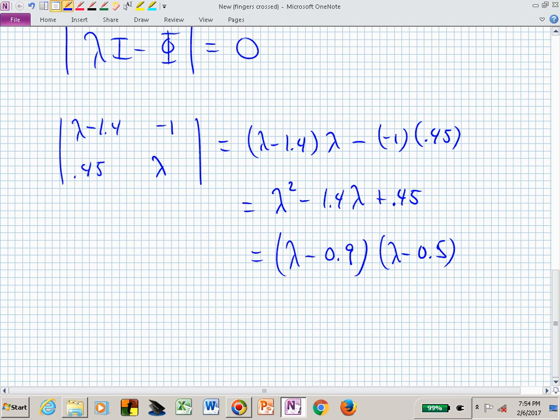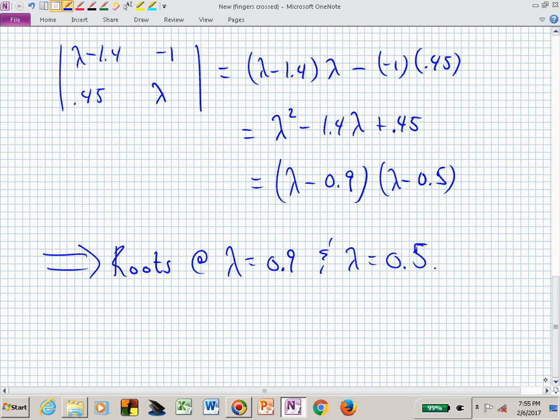and it could give you complex roots, depending on what that quadratic equals. So now I have roots or eigenvalues at values of lambda that cause those factors to become 0, or to vanish. I have eigenvalues at 1/2 and 0.9, or those are the poles of my system.